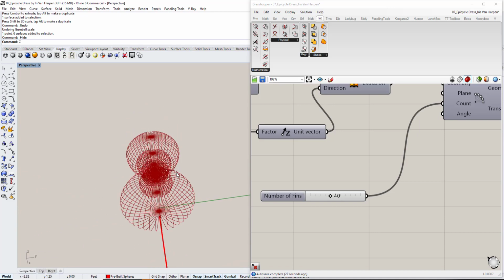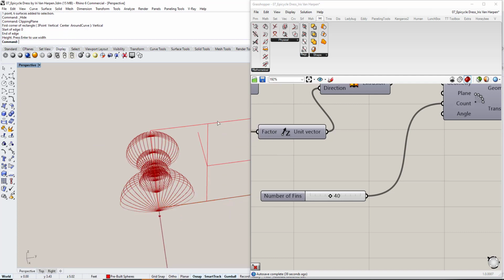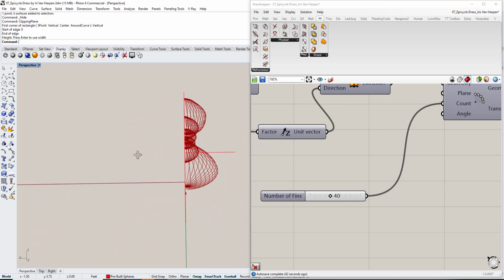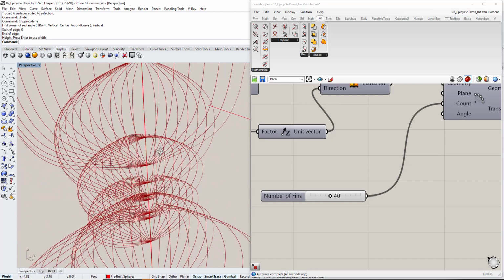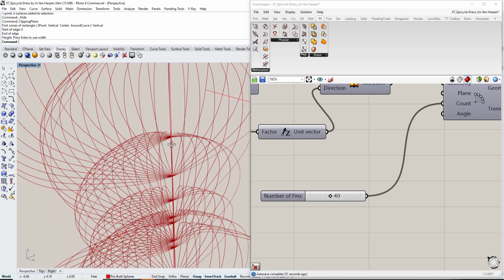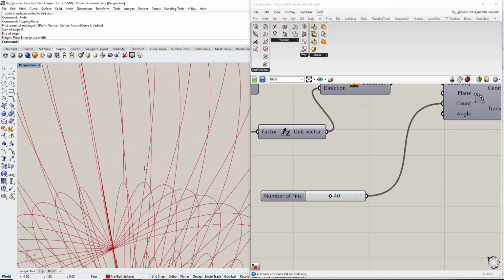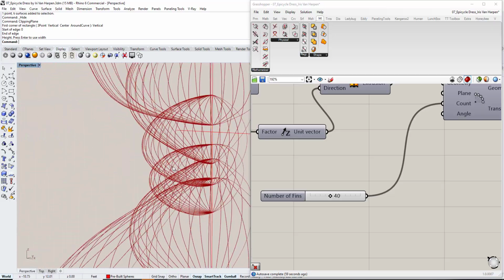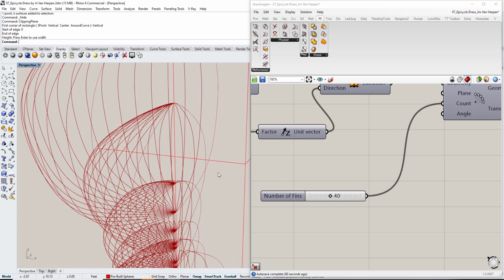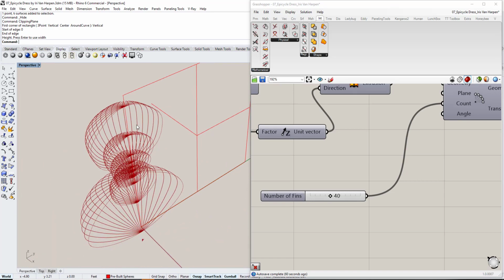So what I'm going to do is actually use a clipping plane. Okay, so if you type clipping plane and then you click this thing called vertical over here, I can start at this 0 point here and just go along the side and create a rectangle. And what it does is it just creates almost like a section view, right? And if I zoom in over here, you'll start to see that the issue is really that all of these surfaces are going to start intersecting each other. You see, even these two lines, it's kind of hard to tell, but when you look at this on your own computer, you'll kind of tell that these curves can't be made out of fabric because each of these pieces of fabric are lying in the same plane and they're technically overlapping each other. So what I really need to do is alternate them, right?